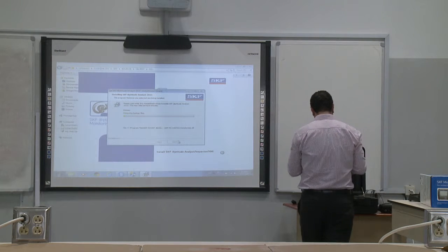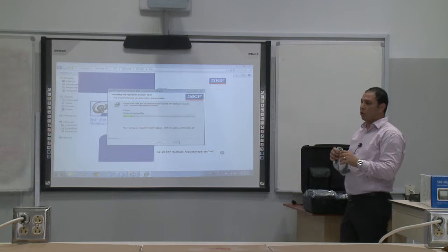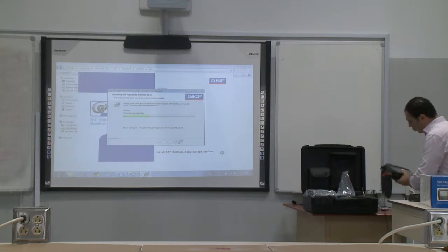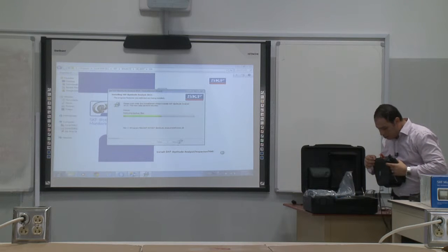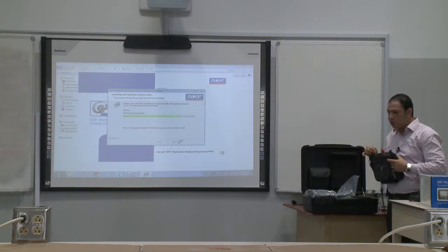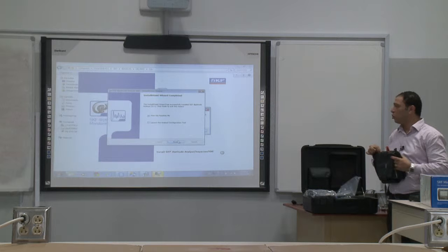And the other side is 6-pin to fit the microlog. In the microlog, you will find here channel 1, channel 2. Each of these 2 channels comes with 6-pin. So the 6-pin cable connects the accelerometer to channel 1 or channel 2.